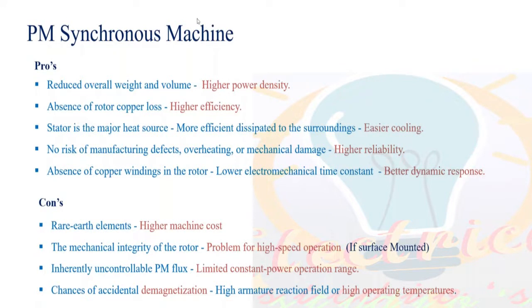And the negative side, yes, PMSM motor also has a negative side. The main negative side is the rare earth materials in the permanent magnets. Because of that, the price of the permanent magnet motors, PMSM motors, is very high compared to BLDC.